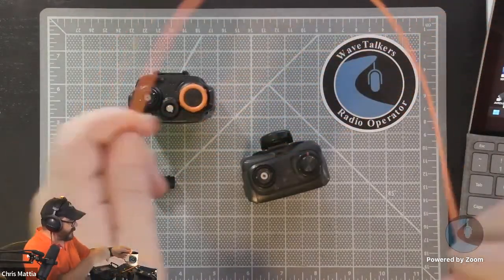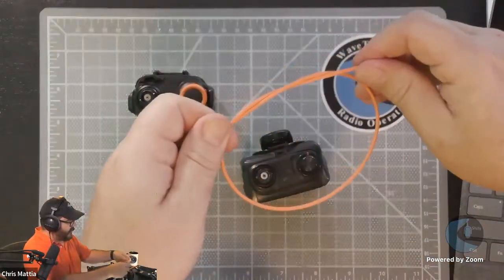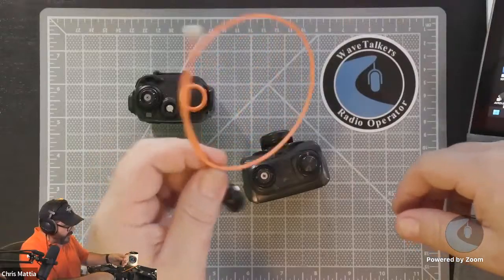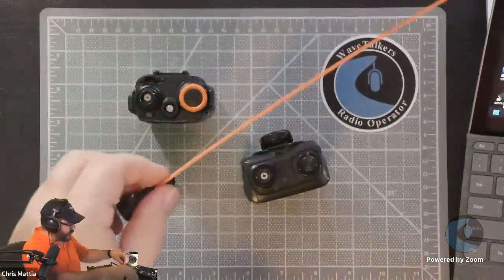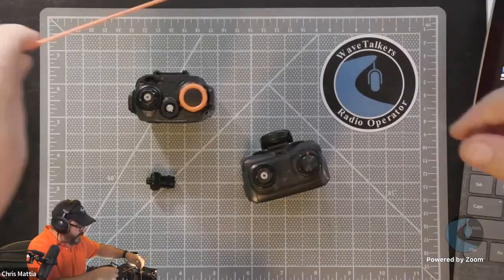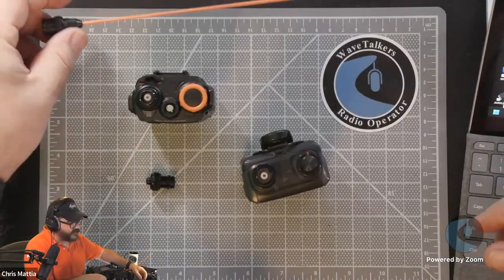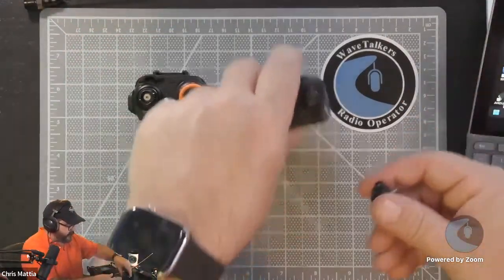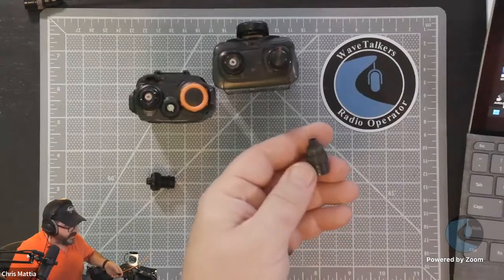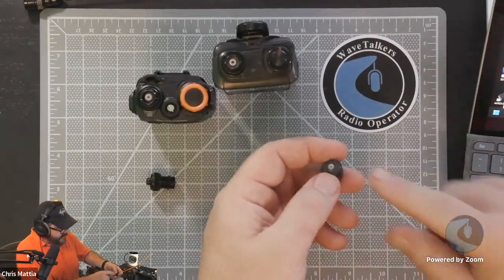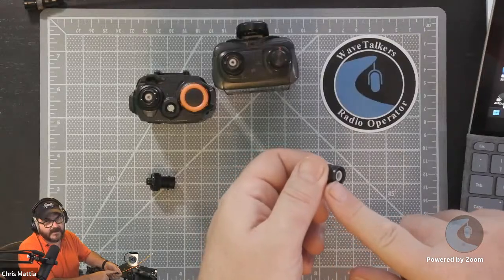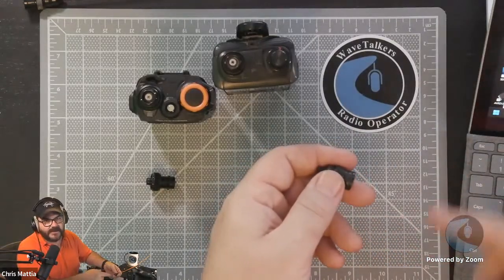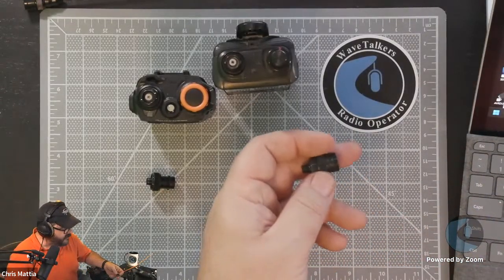One of the things I like about them is you can roll them up, and they pack away pretty small, and then you can extend them out. They have really good range and quality. What I typically will do is put an adapter on all of my existing antennas that has the correct SMA adapter, and then it goes into the BNC. So it makes it very easy to change an antenna from one radio to another.